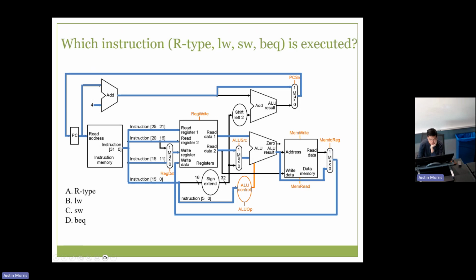So the rest of the instruction, and then we're branching off down here for the last 6 bits of the instruction. This is the func code. So again, that tells me this is R type, okay? And then out here, after the register file, this is RS, this is RT, because we knew that from these. And we're selecting RT. So RS and RT here doesn't immediately tell me this is R type, but it does exclude load word, store word, right?